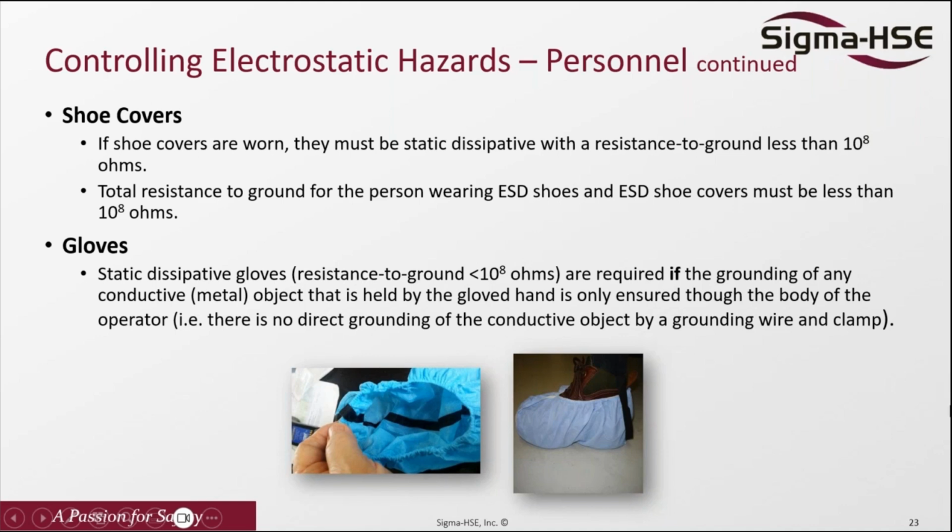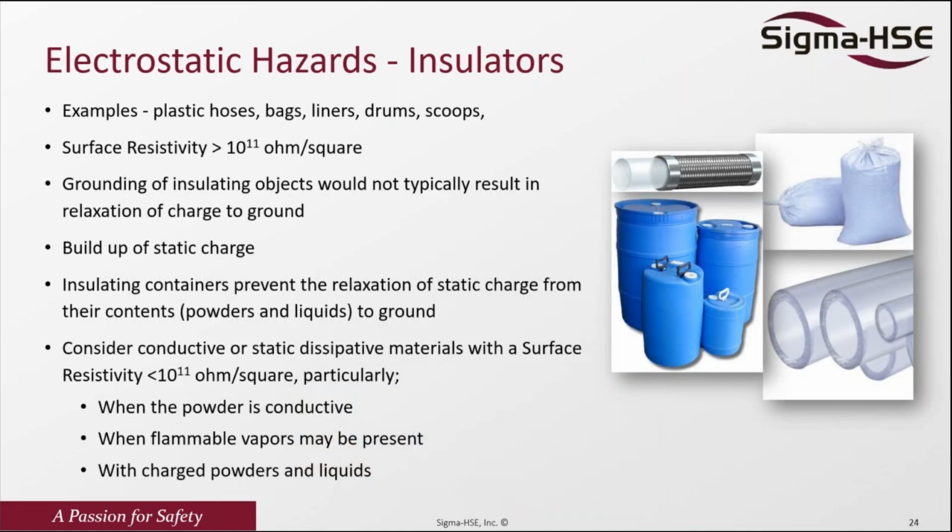If it's a shoe cover, you can see you have the static dissipative strap in the middle, which will actually touch the ground, and the ground needs to be static dissipative, conductive, or it needs to be bonded and grounded. Sometimes we could also use gloves, which are also used when we are trying to transfer porous materials. What about insulative materials?